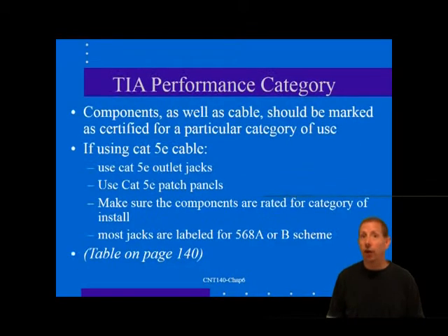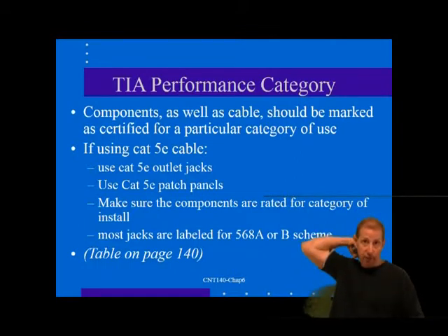You can make a very good argument that the TIA 568C wiring system is as close to a universal wiring system as we will ever get. Of course, there will always be situations that do not fit this standard model, but more and more equipment is being designed to take advantage of its characteristics. If you choose to diverge from the standard to implement some of the 2-pair technologies, for example, you may be left out in the cold in a very short time.